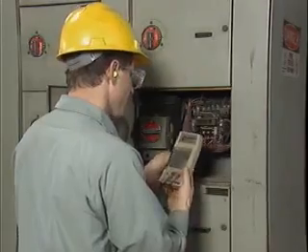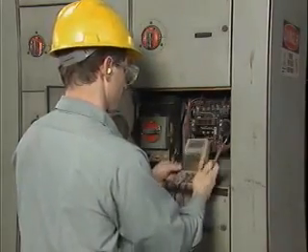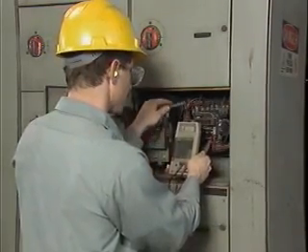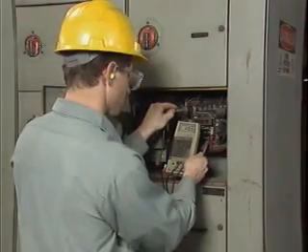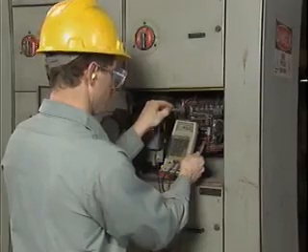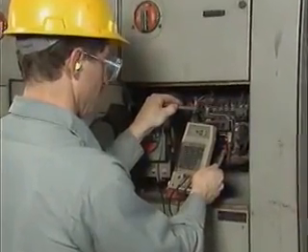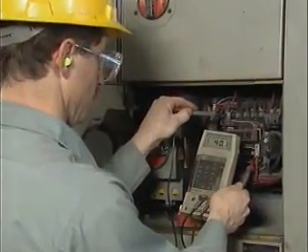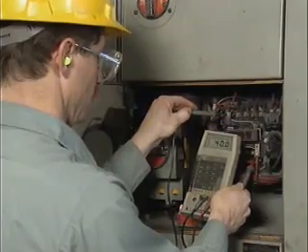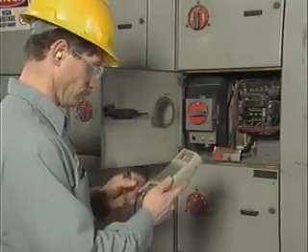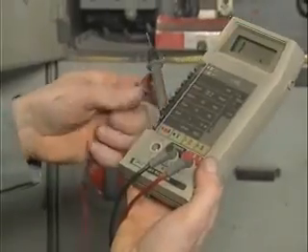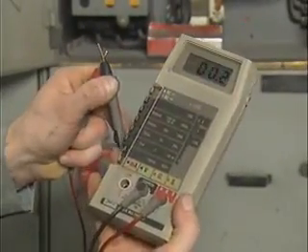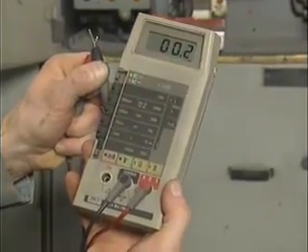Another test that is commonly made on de-energized controllers is the test for opens. One way to test for opens is to use a multimeter set for resistance. Each component under consideration is tested by placing the multimeter test leads on the component's electrical connection points. When a component is tested for opens, the component's resistance is measured. The first step in using a multimeter to test for opens is to zero the multimeter. On this multimeter, the electrician selects the appropriate resistance range, then touches the multimeter probes together to zero the meter.